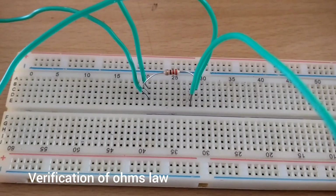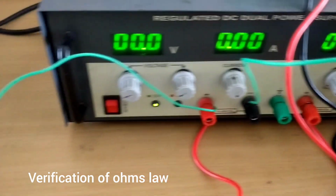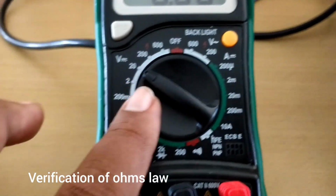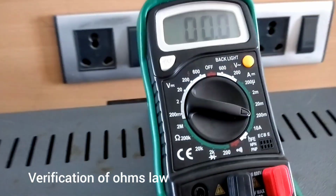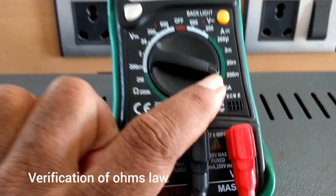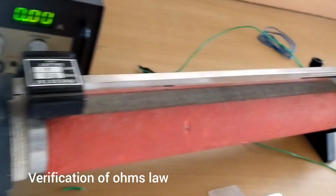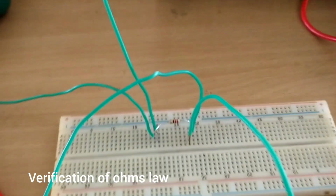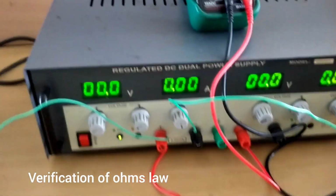The connections are given as per the circuit diagram, and this is the RPS. You can see this multimeter acts as a voltmeter. It measures up to 20 DC volts, and this acts as an ammeter. This measures 200 milliamps, and this is the rheostat. We have given the circuit connections as per the circuit diagram.